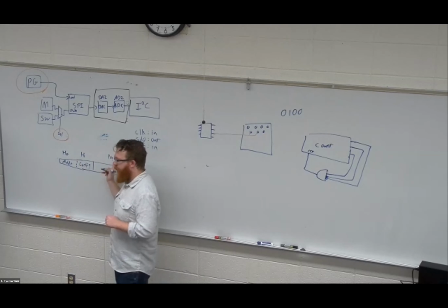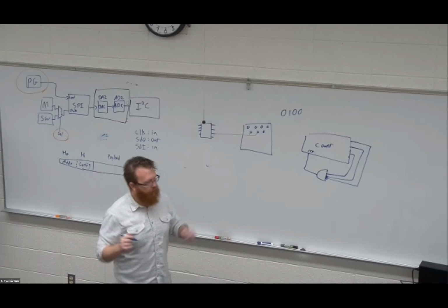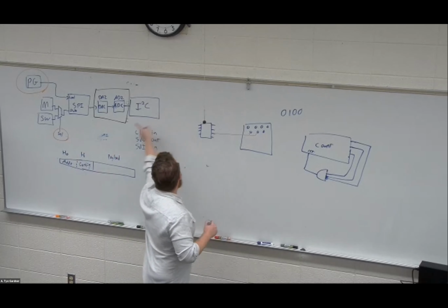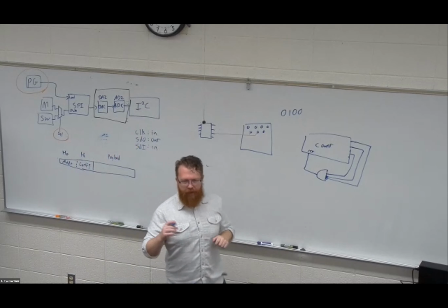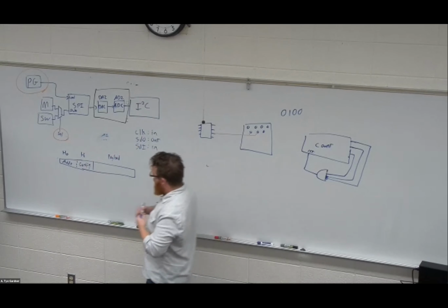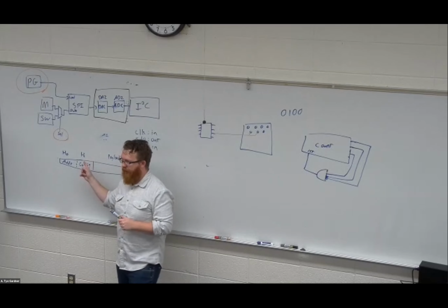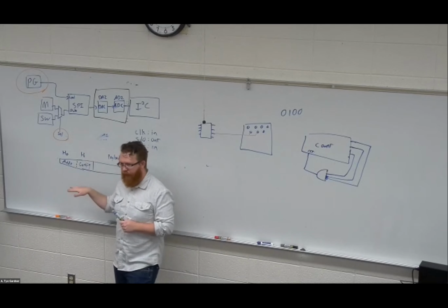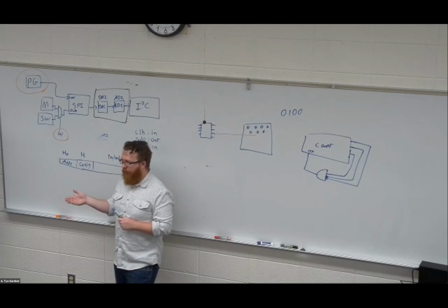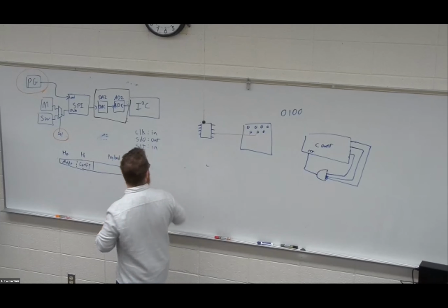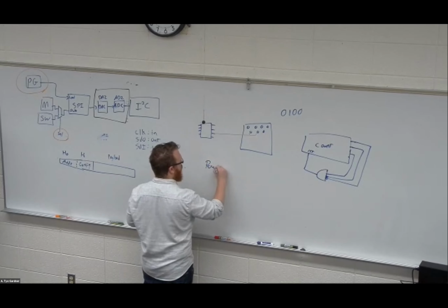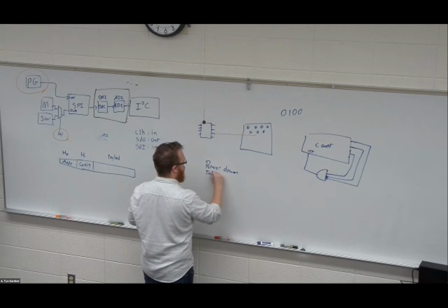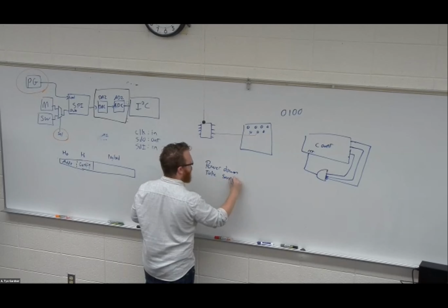If it is their address, then they go look at the header part 1, which is, what do you want me to do? Then the last part is the payload, which is do this, right? This configuration in the payload can work a couple different ways. And let's do it in context of the ADC. So the ADC could receive a power down command, for example. Now, it could have this power down command in the config if I have enough bits and it just powers down. Or, well, let me do this, right? So power down could take a sample.